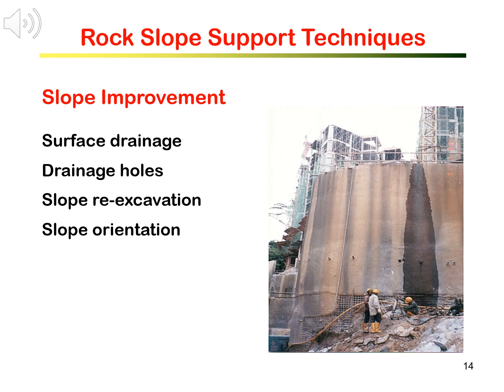Slope re-excavation is another option to be considered to reduce the risk of slope failure. There are possible situations where reducing slope angle can help in reducing the risk of slope failure. One is for very poor rock mass. Having a lower slope angle closer to or lower than the slope rock mass friction angle will lead to a safer slope or require less support.